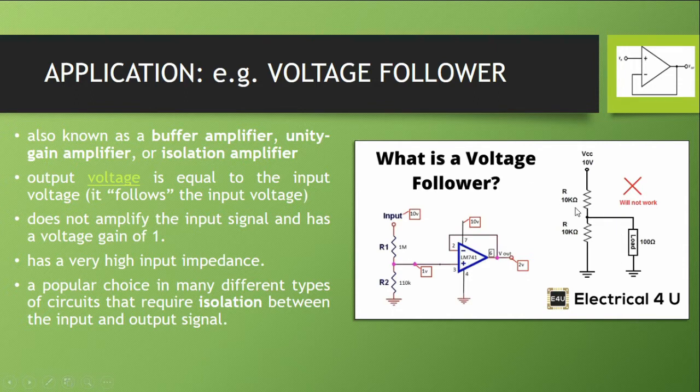Here on the right shows that a 100 ohm load is connected between two 10K resistors, which serve as the voltage divider. This will not work in real life.